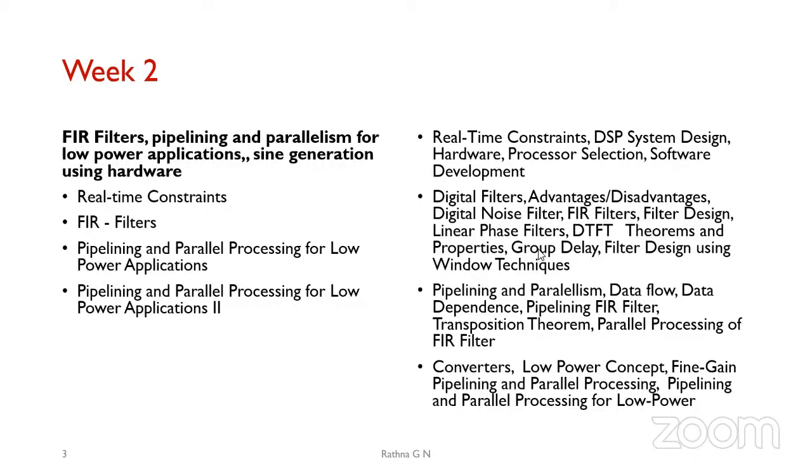Here we are using an inbuilt hardware of a DSP processor, which is given by TI in this case, and we are working on the real-time part of it. Here also you have constraints. When you have your own constraint on real time, within one clock cycle you have to get your output, which is going to involve, as I mentioned, your computation time as well as your IO bandwidth. Basically, all this has to be taken into account.